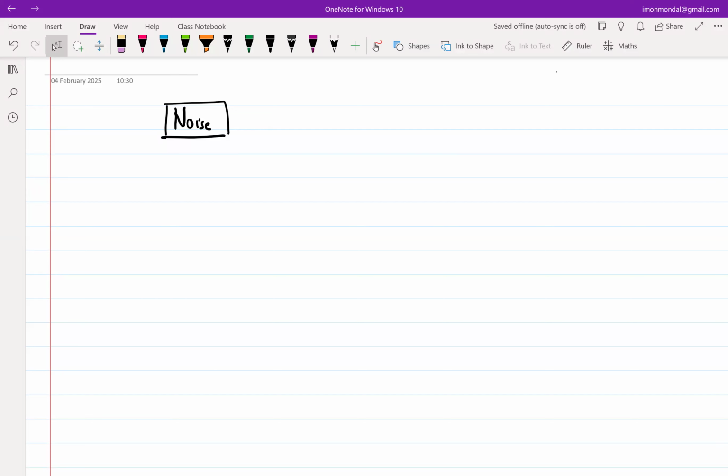So the local oscillator frequency we moved away from the reception frequency. That helped in reducing the out of band emission. That also helped in ensuring that whatever is coming through as an input does not fall into the range of inputs that is of interest to us, right?